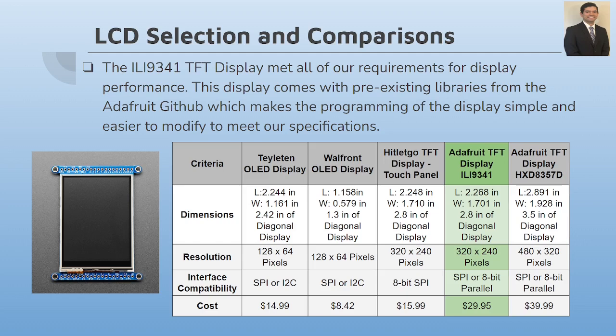This is because SPI has a higher data transmission speed between the MCU and the display than the I2C interface. We needed this higher refresh rate to ensure that the graph of power over time was going to update accurately and in real time.